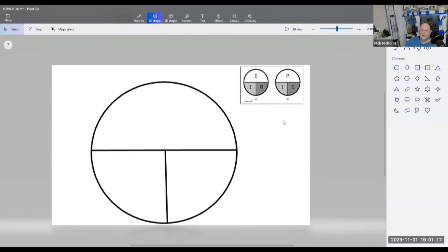Remember the PIE, the pi formula, or the EIR. I'm sorry I don't spell EIR right, but hey, it works for this. These two equations, this is the simplest way to do it. If they give you the power is 120, put that 120 watts up in the top right here.